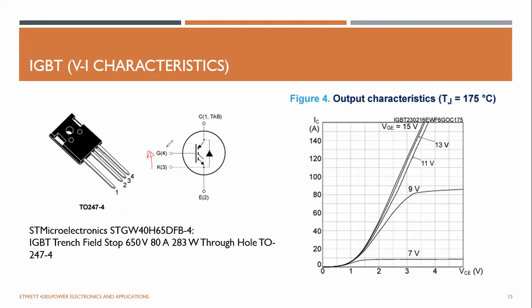Just go and look into that. As I mentioned, driving the IGBT is not easy, so you can't just drive it from an Arduino. You have to have a gate driver. For gate drivers, sometimes it is desirable to have a direct pin across the emitter rather than using this one.